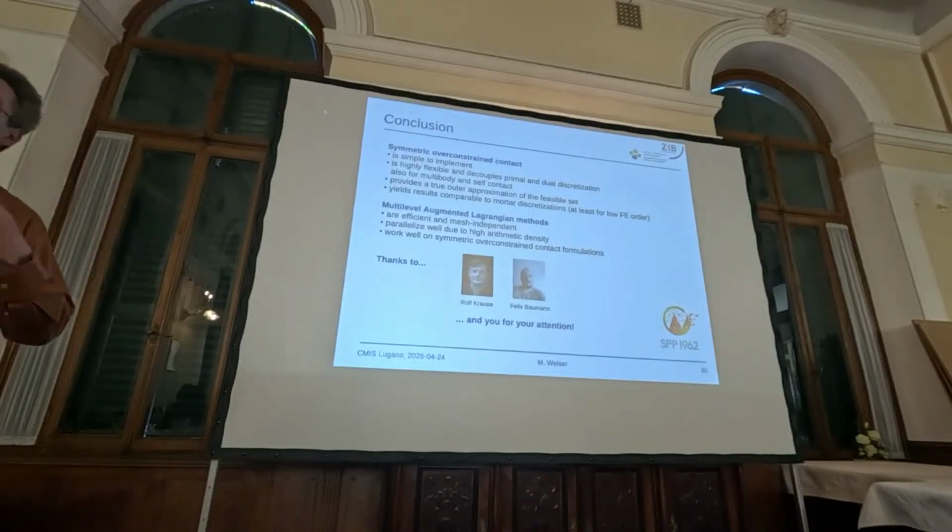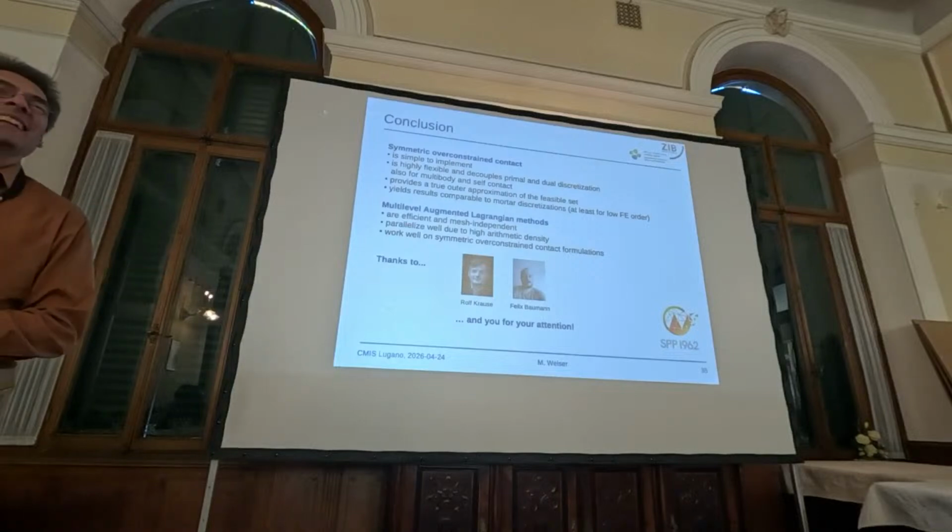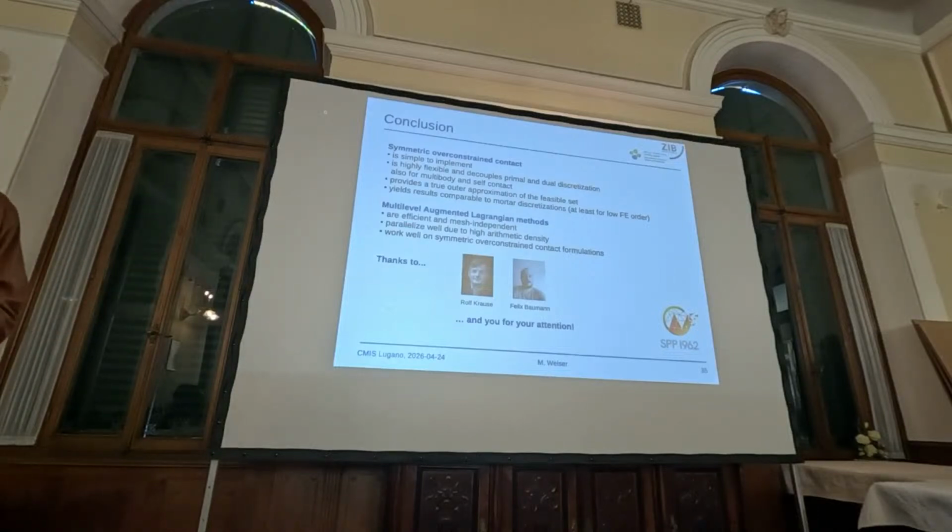And in total, this package appears to be quite useful. Of course, there are limitations and caveats. There is so far no discretization convergence theory, and you get the usual penetration with penalty and augmented Lagrangian formulations and so on. So it's not the best method for everything, far from that, but I think it's an interesting approach to study.